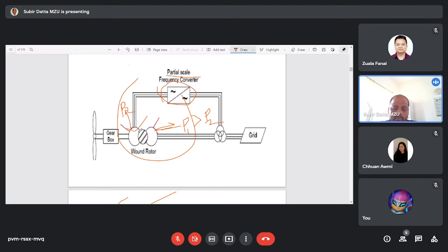Okay, so what is the difference between these two? Both are stators. The difference is the pole number. For the primary stator the number of poles is P1, and for the secondary stator winding the number of poles is P2. So these two are different. Which one is more? P1, the number of poles for the primary stator winding, is more than the number of poles for the secondary stator winding. So this is the condition. The difference between these two is their pole numbers.